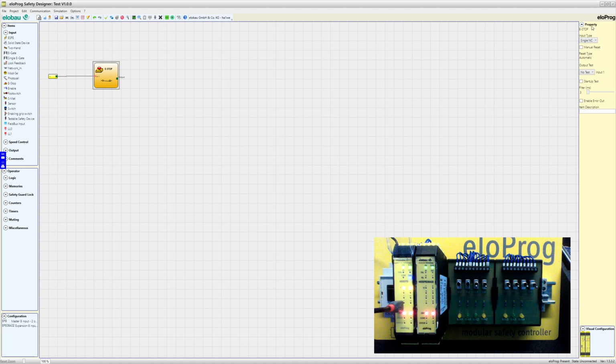And on the right side, you have the capabilities of this block. What can you have as an option to choose? You can have just a single, normally closed contact. Mostly we have e-stops with two contacts, so I choose double NC. And now we have to assign this input to a terminal, a physical terminal on our module.